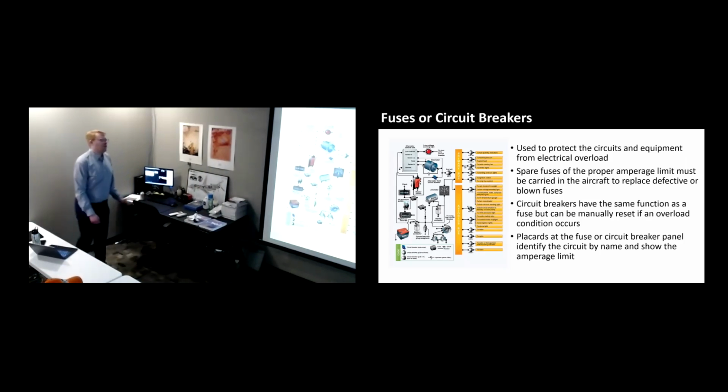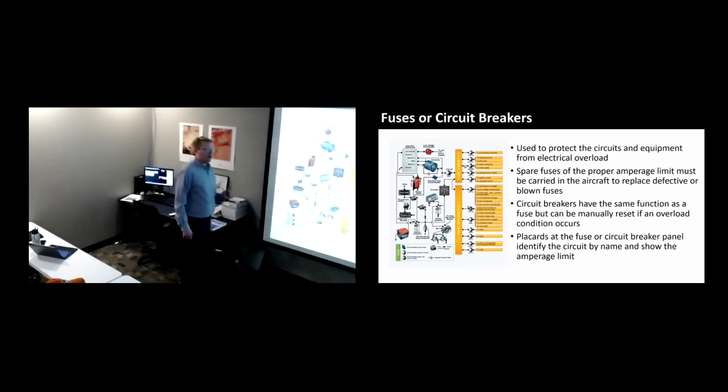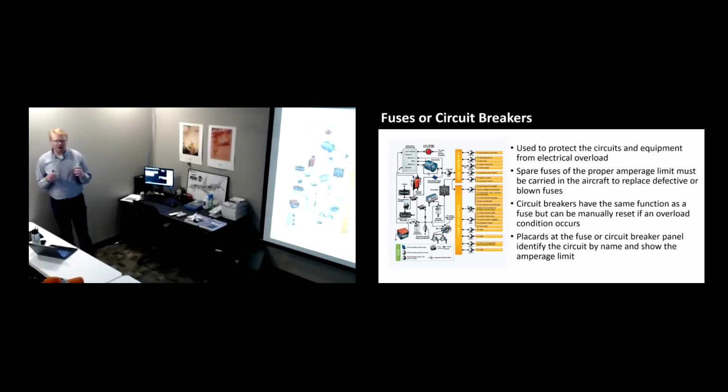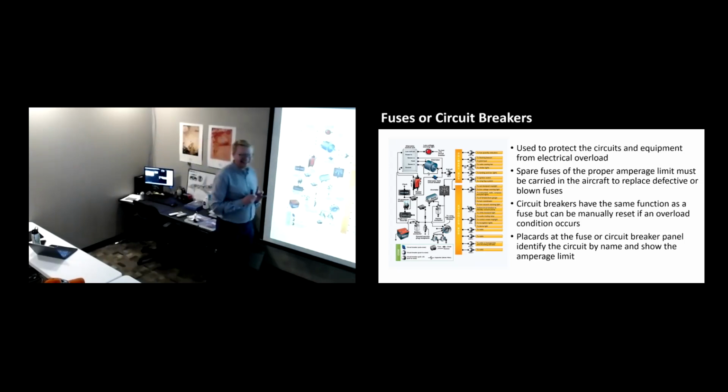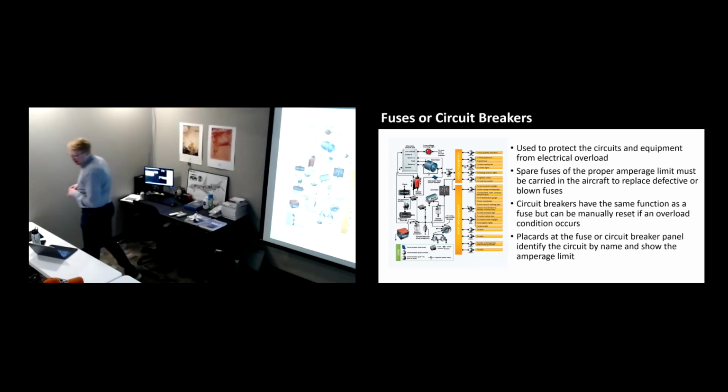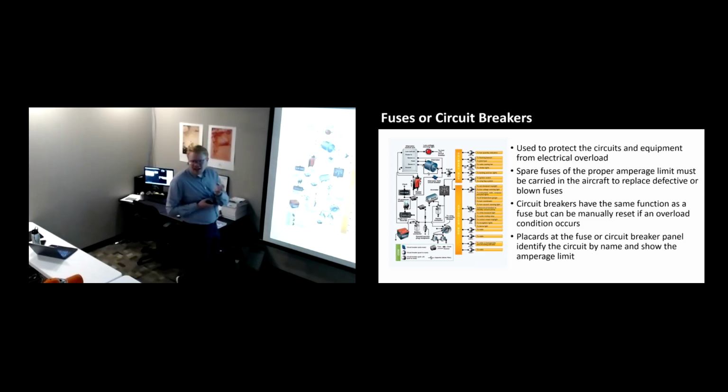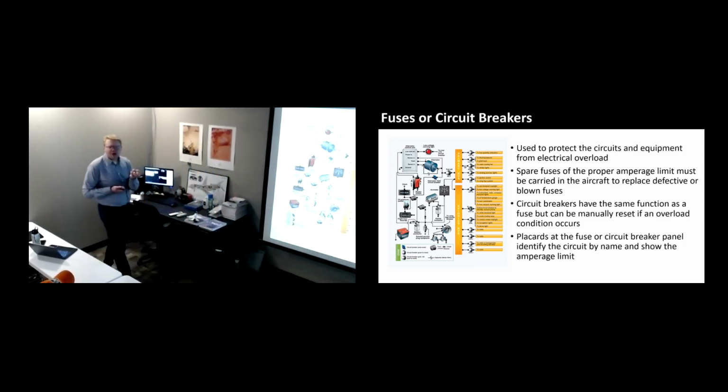Sure. Fuse. Old style fuse design is in a little tube. Some of you may have had a fuse in your car, where you had to replace a little tube in there. Basic thought of this is you have a wire inside of a tube you're applying current through, and the wire is rated to a certain current value, amps. If that value is exceeded, the current going across it goes up way too high. Usually the resistance bumps up a good bit in there. That heats that wire up, and when it hits a certain current value, it melts itself and disconnects the connection and shuts that component off.